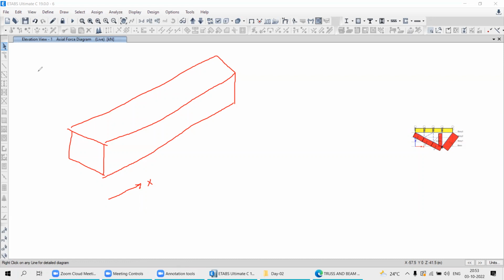Okay. Now, two axis systems are mainly, actually three are there, but the most important are two. One is your global axis system, another one is what? Local axis system. Okay, global and local. So global axis system is where the software shows X, Y, and over height Z. But when you come to the local axis, meaning the member axis, it is along the longitudinal direction of the element.